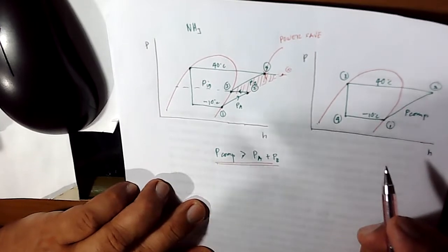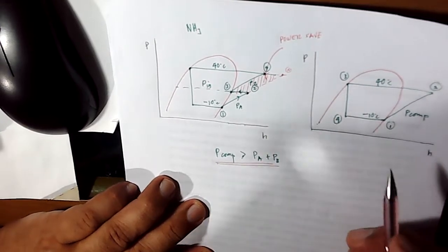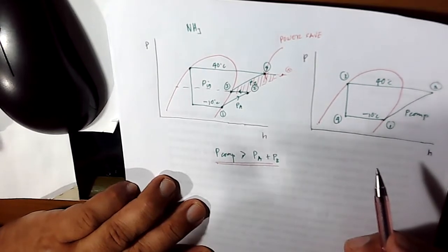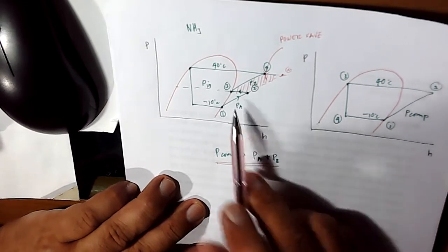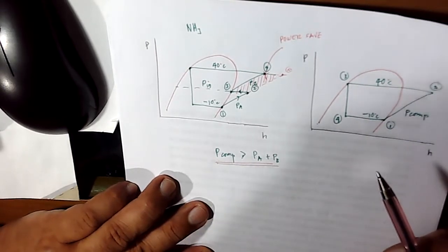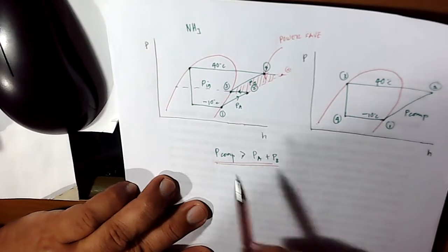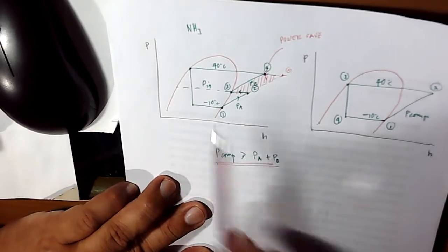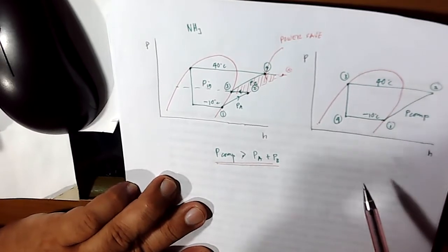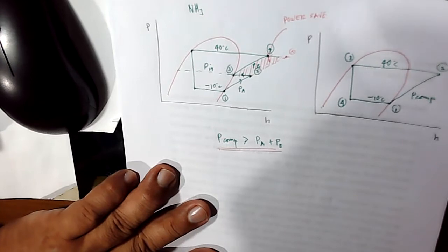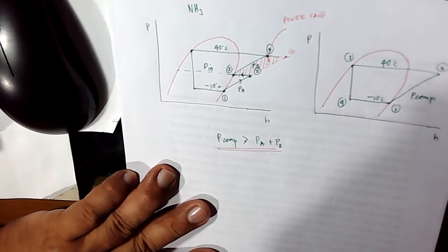If there is no difference between the two computations, then your computation using the intercooler is wrong. There should be a power save by using this intercooler. Again, it is intercooling with the use of a water-cooled heat exchanger.